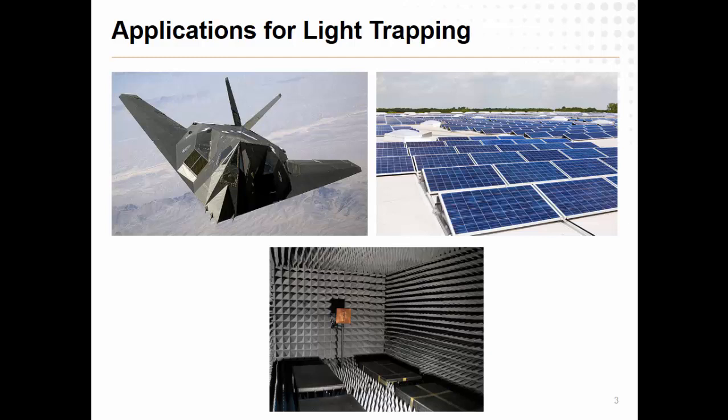You probably can't see it with the lighting really well. But again, the idea is I want to measure the directive pattern of an antenna, so I have to illuminate it with some plane wave, but that's going to create scattering and bouncing and reflections everywhere. And when you're inside a big metal box, that can corrupt your measurement. So what we do is we coat the walls of our chamber with this special anti-reflective absorbing foam. So any light or radio waves that hit the wall get absorbed inside the walls rather than create an echo. That's where the name comes from, anechoic, or non-echoing chamber.